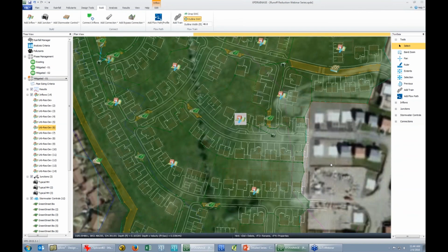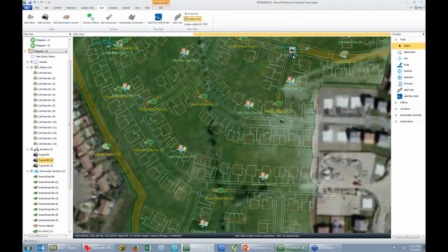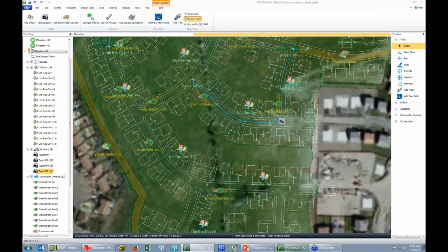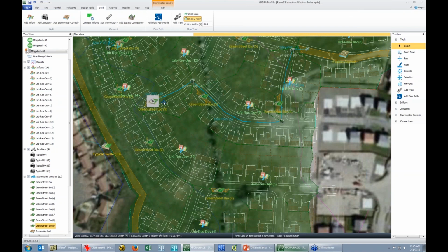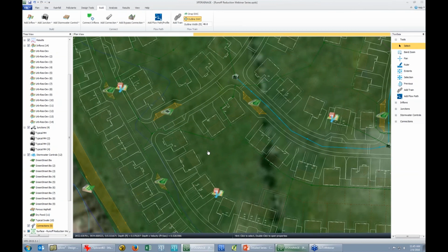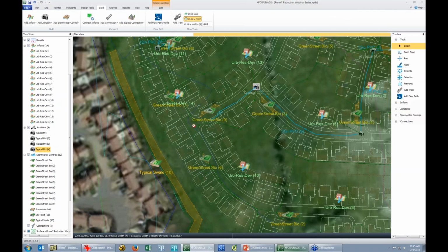So all we would do now is just right click, and we could connect our facility. I happen to have this 12-inch PVC pipe we might start out using here, and we could connect our facility as we work our way downstream. So just to show that drainage system, maybe I'll add in a couple more manholes. We could show this would drain. That actually snapped the wrong thing here. I'll just delete this one. So you say this could drain into that swale. So we might have a daylight pipe pops out into that swale. And I will say perhaps this goes between some property and connects. Daylight's right out there.